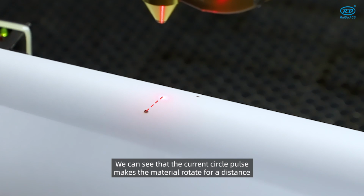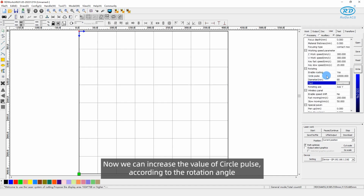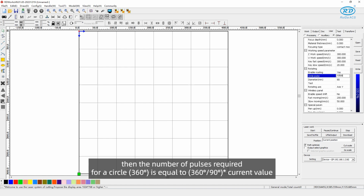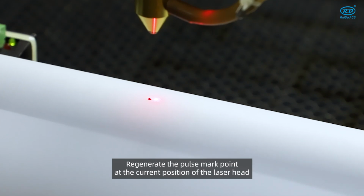We can see that the current circle pulse makes the material rotate for a distance, but it's still some distance from the starting point. Now we can increase the value of circle pulse according to the rotation angle. For example, the current value makes about a 90 degree rotation. Then the number of pulses required for a circle is equal to 360 degrees divided by 90 degrees, and then multiplied by the current value. Regenerate the pulse mark point at the current position of the laser head.